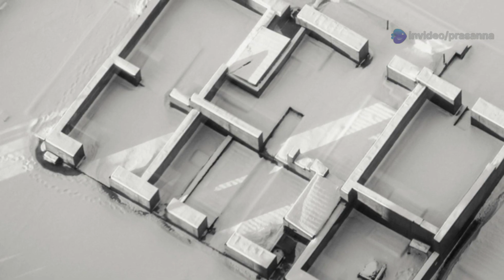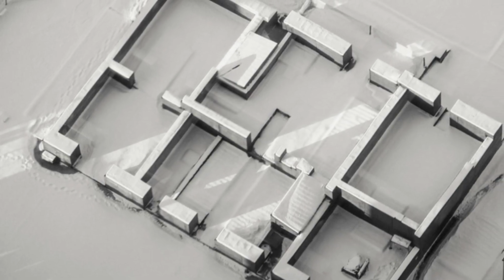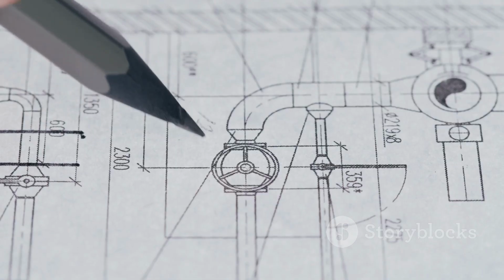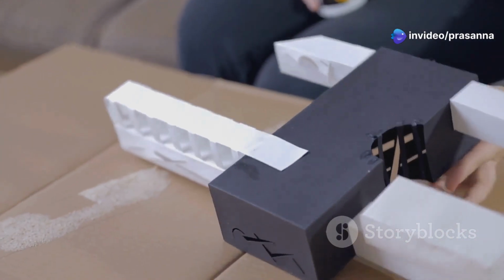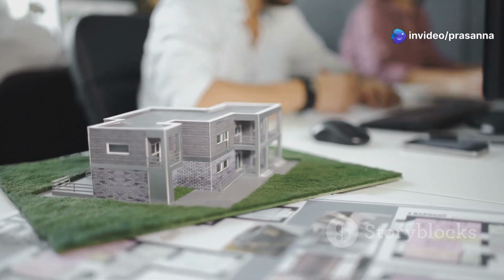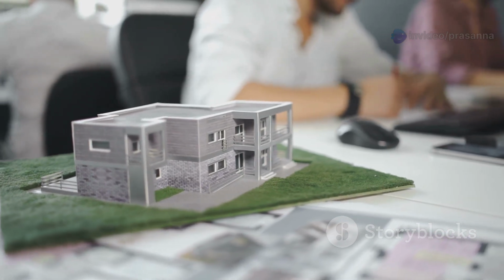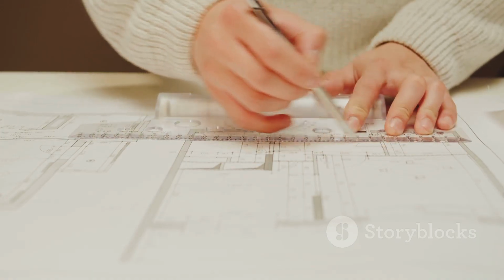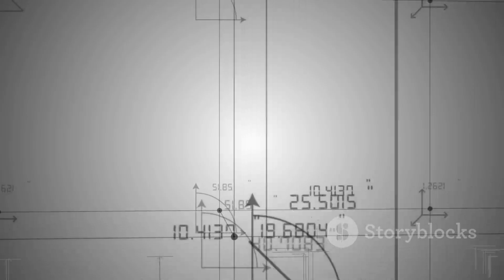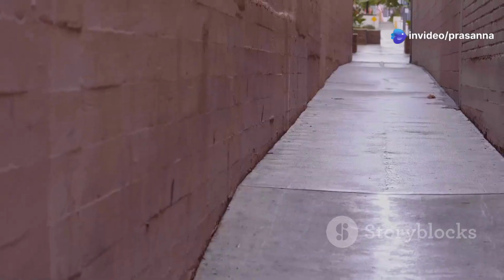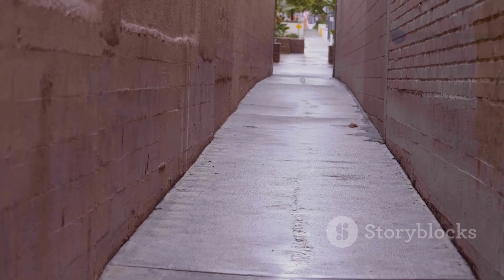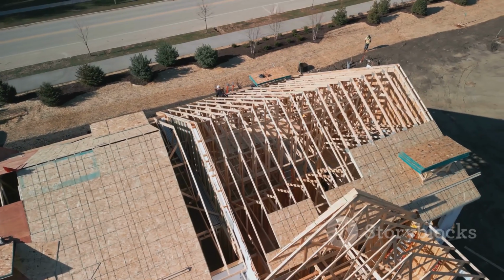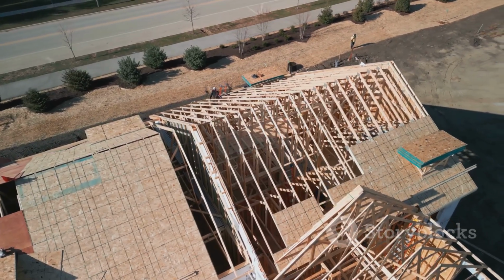You can start by drawing the outline of the roof on top of the walls. Then use the Line tool to draw a ridge line. Use the Move tool to pull the ridge line upwards, creating the slope. SketchUp's Follow Me tool is also very useful for creating complex roof shapes. You can draw the profile of the roof, a cross-section view of its shape, then draw a path along the edges of your walls where the roof should sit. Select the path, then activate the Follow Me tool and click on the roof profile. SketchUp will extrude the profile along the path, creating the roof.